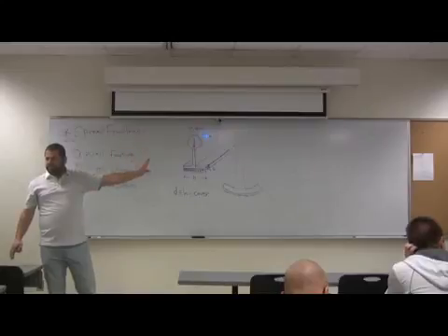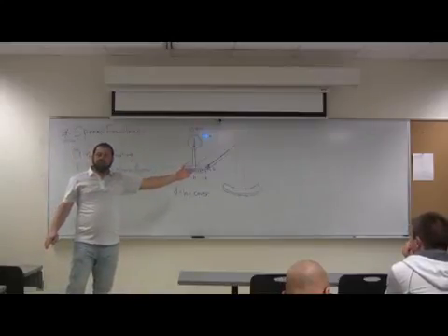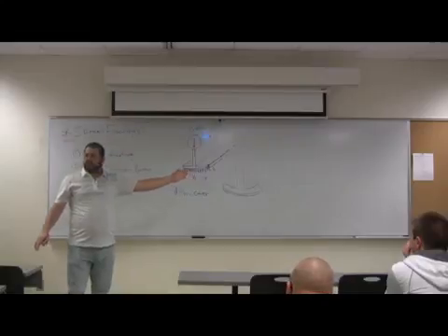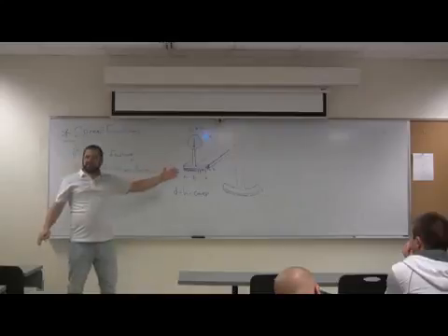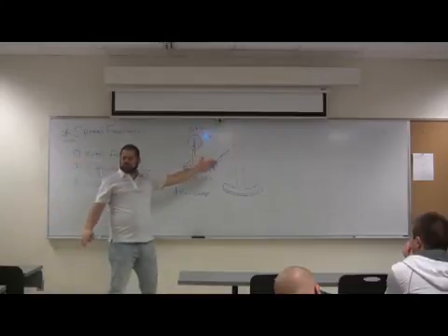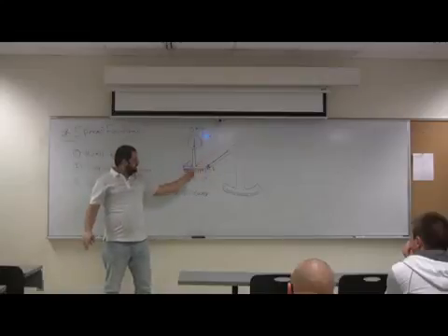We will check shear, but we don't provide stirrups in the foundation. So the concrete supports the shear. The thickness of the footing must give you enough phi Vc to resist the ultimate shear at the critical section.